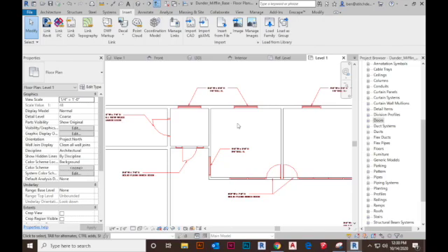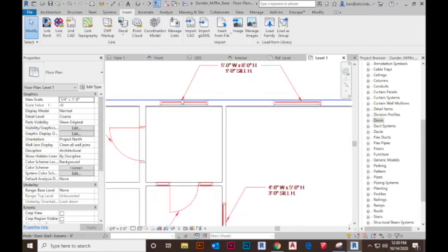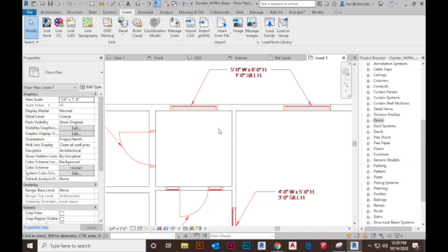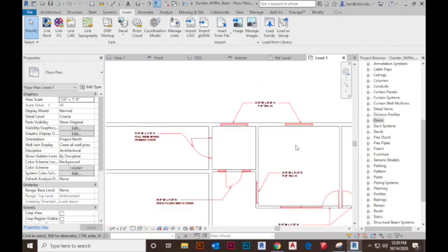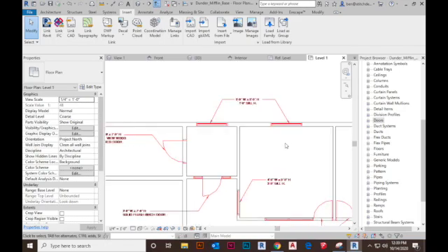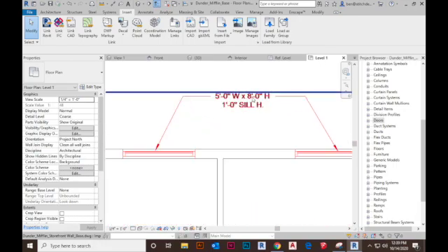What that does is it keeps all of our live model elements on top of that CAD document, but wherever there is something inside the perimeter of that wall, like this cut-in curtain wall layout, we'll see that red. And when we draw on top of it, because it's set to the background, that will disappear and let us know what we have drawn of our model elements and what we have not. So we can see each one of these windows or doors have some dimensions set to them, a width dimension, a height dimension, and then a sill height from the finished floor dimension. So that 1 foot sill height means that the bottom of that window is at 1 foot above the finished floor.